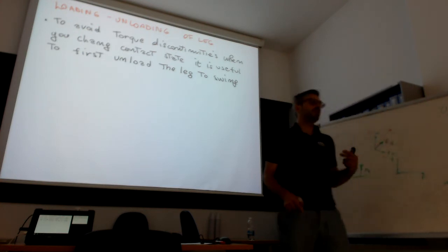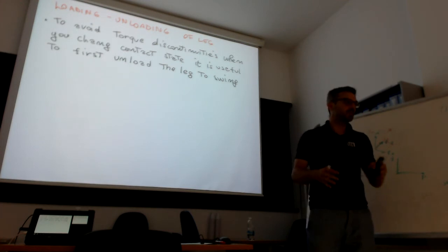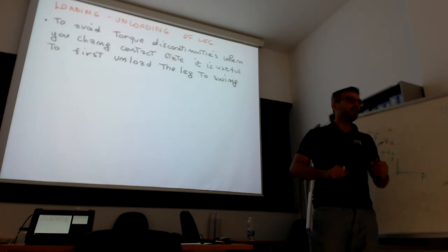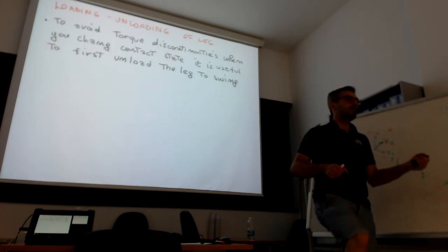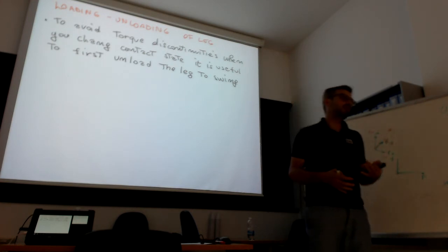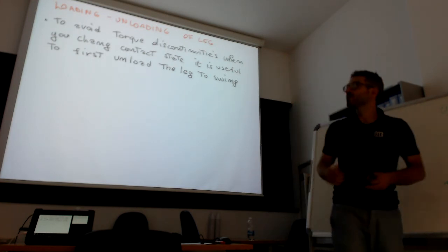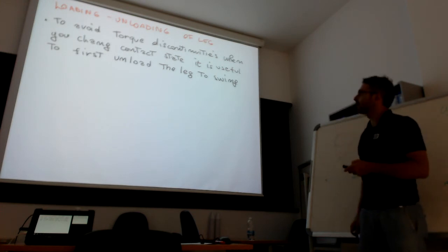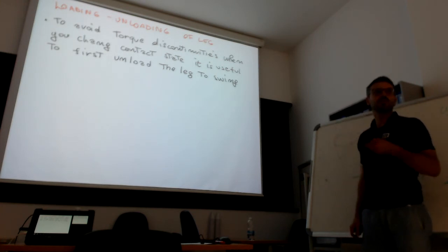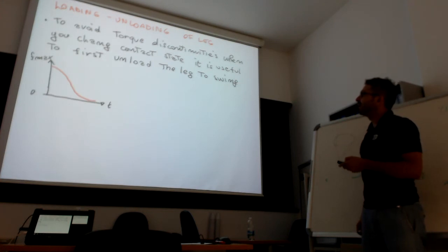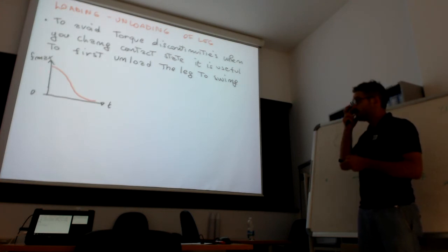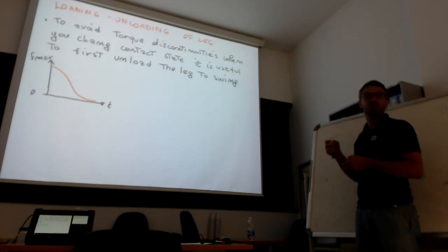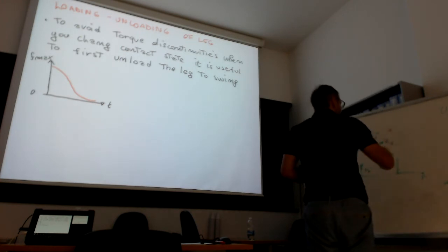This way we avoid the torque discontinuity, because if you change the size of the JP matrix and you didn't do any unload, now immediately, bam, you create a discontinuity in the joints. So unloading the force is very good for the structure of the robot, for the mechanics, and normally you do a spline, you do a polynomial on the constraint itself. So you remember the AC matrix.